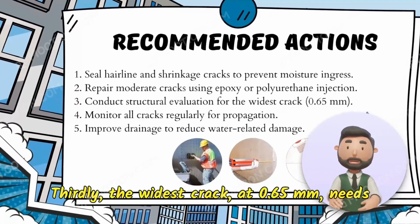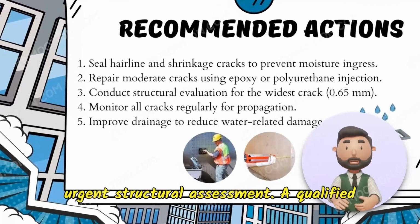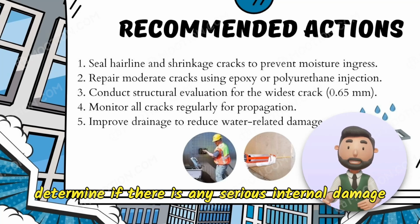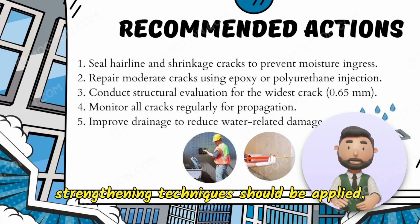Thirdly, the widest crack at 0.65 millimeters needs urgent structural assessment. A qualified structural engineer should inspect this area to determine if there is any serious internal damage or load issue. If necessary, reinforcement or strengthening techniques should be applied.